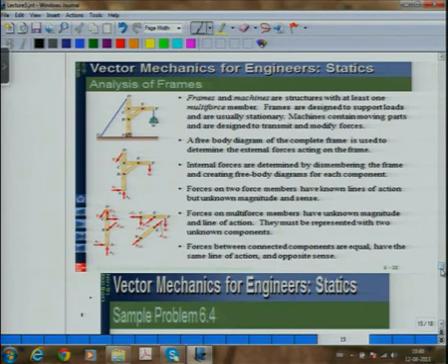But again, you realize that if I use the fact that BE is a two force member, that will simplify my calculations. Otherwise I have to draw a free body diagram for BE also. So when we have a multi-component frame, try to see what you can make use of, because you may have to break the frame into parts to be able to solve for this.